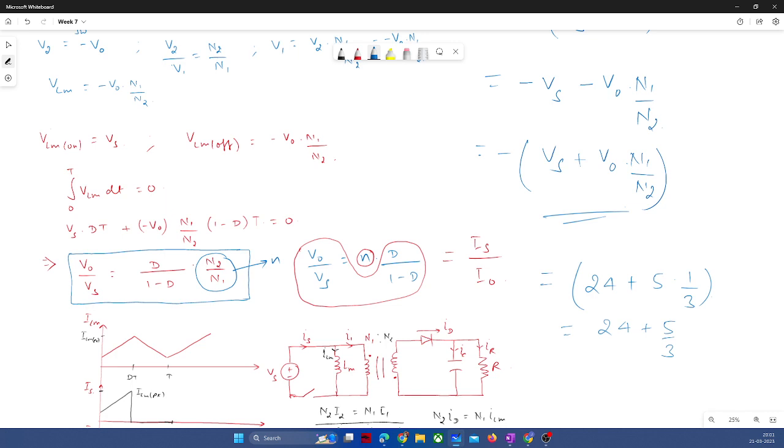Since the inductor voltage is reversing at that time, the voltage across the switch will settle down to this value of 25 point something, but at the instant of switching off it will be of a higher value. So if it is higher than this, then we will have to design according to that value.